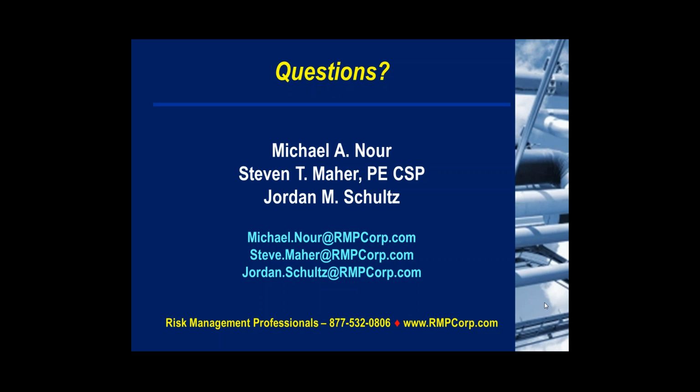Okay, yeah. Just one thing to add on to both of those is the fact that PHA revalidations have to look at MOCs within the past 5 years and incident investigations for the past 5 years. Hypothetically, when you do an MOC, you should be checking the hazards and doing a mini PHA if it's a big enough change. And so when you do your revalidation PHA and you look back at those MOCs, it's really just a check, if you will, to make sure that the original MOC covered any additional hazards that were introduced.